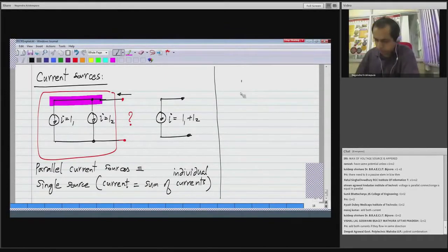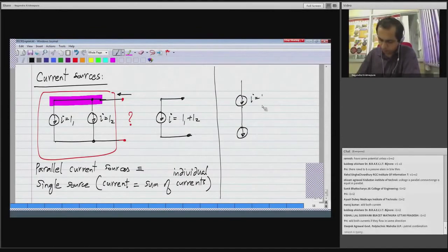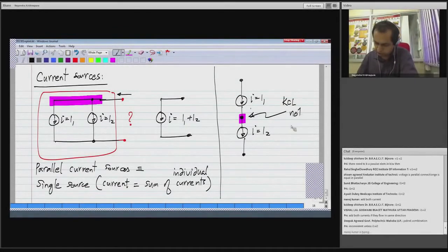And we can quickly look at what happens if we have current sources in series. Just like with voltage sources in parallel, unless I1 happens to be exactly equal to I2, KCL at the middle node is not obeyed if I1 is not equal to I2.